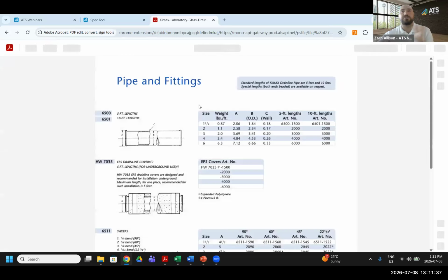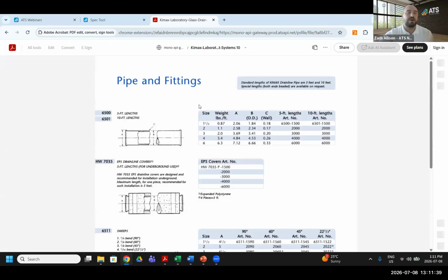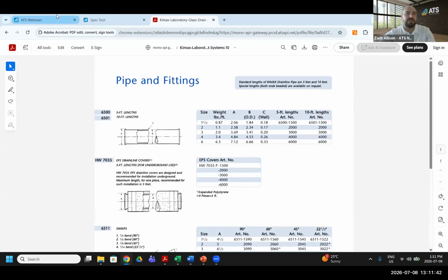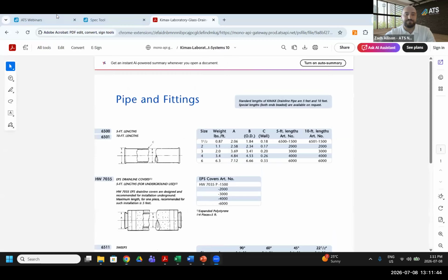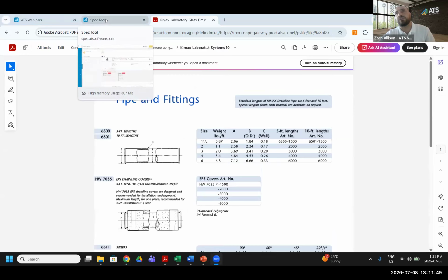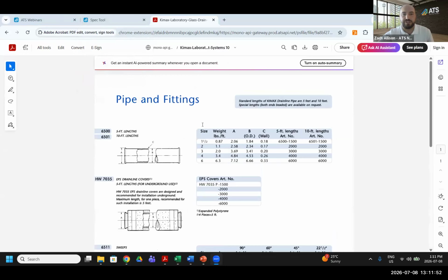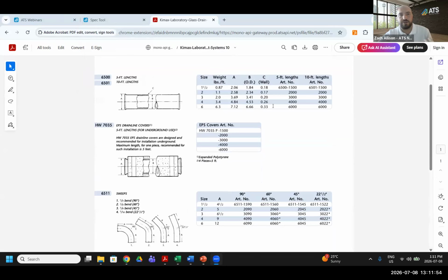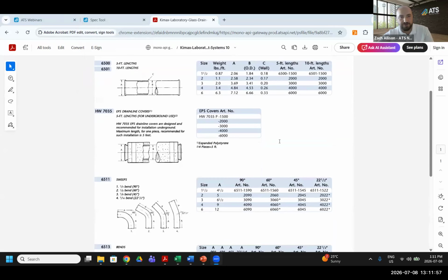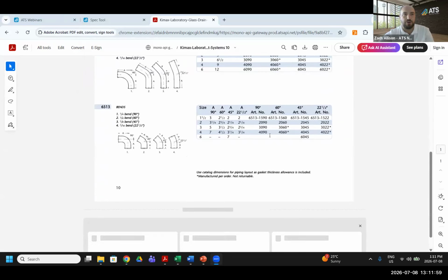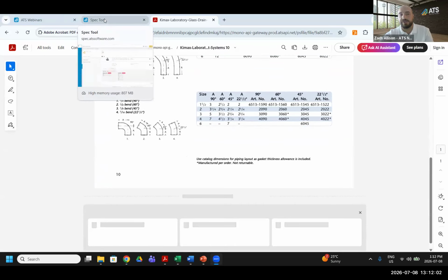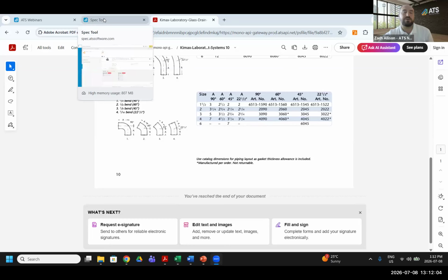So if you want more details on flow rates versus pressure drops for sizing your backflow, or if you want to understand the recovery capacity of your water heater or anything like that. All the manufacturer sheets with all their flow curves and particular details. In this case, the lengths, the weights, diameters, inner diameters, everything like that, all your curves. Those are all included in the manufacturer spec sheet, and then you can configure your selection to match exactly what you need for your particular project, master, or quick spec.